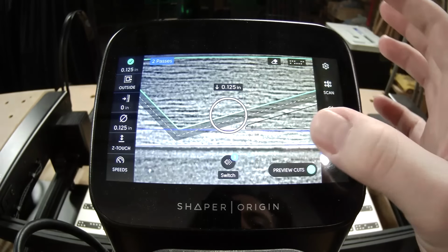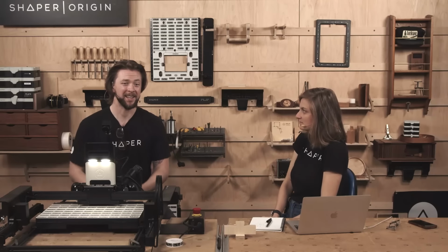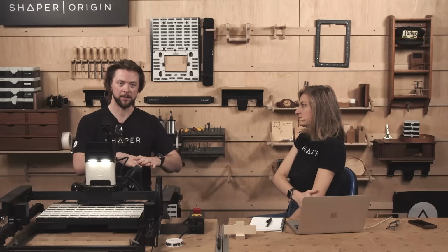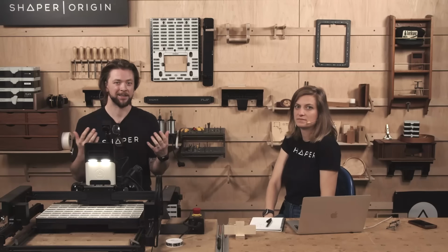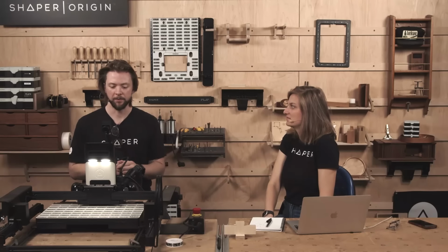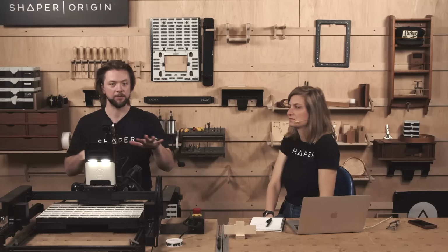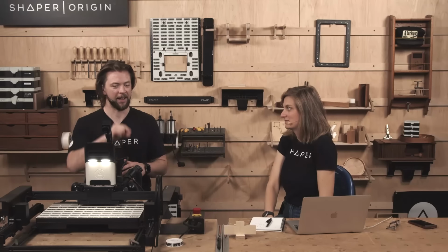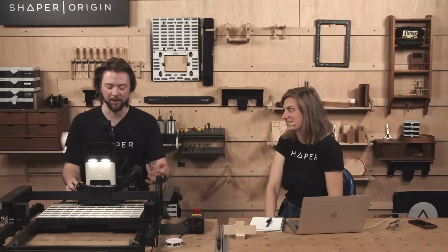Great. One thing I do want to add is a bit of a negative offset. And this comes from just having cut these before. Anytime you're cutting an inlay that has a bunch of parts coming together into a pocket, you have so many competing surfaces that if you cut everything to 0, sometimes it doesn't fit, even if you're taking a negative offset off the pocket. So what I've found is that taking a very small negative offset off of each of the components kind of gives everything a little bit of breathing room to actually come together. Especially on these star inlays, everything likes to fit until that last one. So it's a compounding, not error, but compounding tolerance.